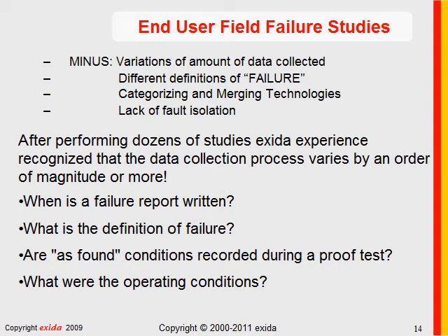Well, remember that for dangerous failures in an automated safety function, a dangerous failure will not cause the process to shut down. That's a safe failure by definition. Dangerous failures are only known and discovered during what's called a manual proof test.